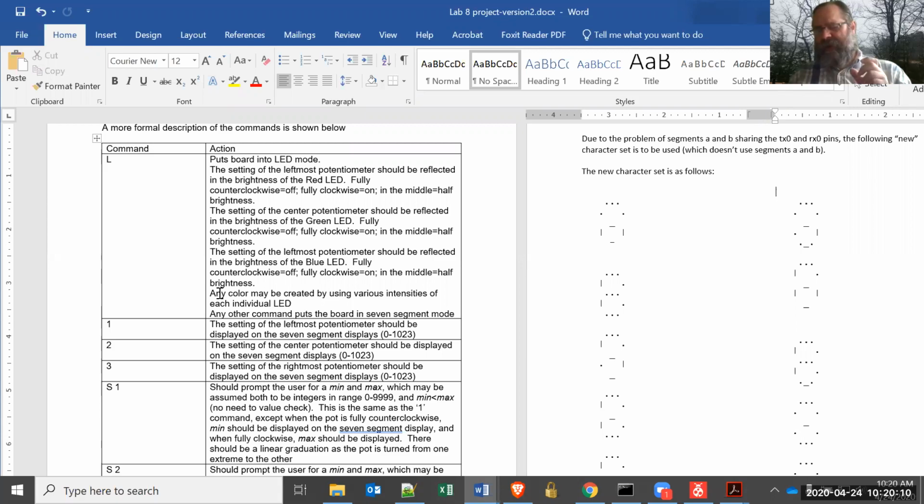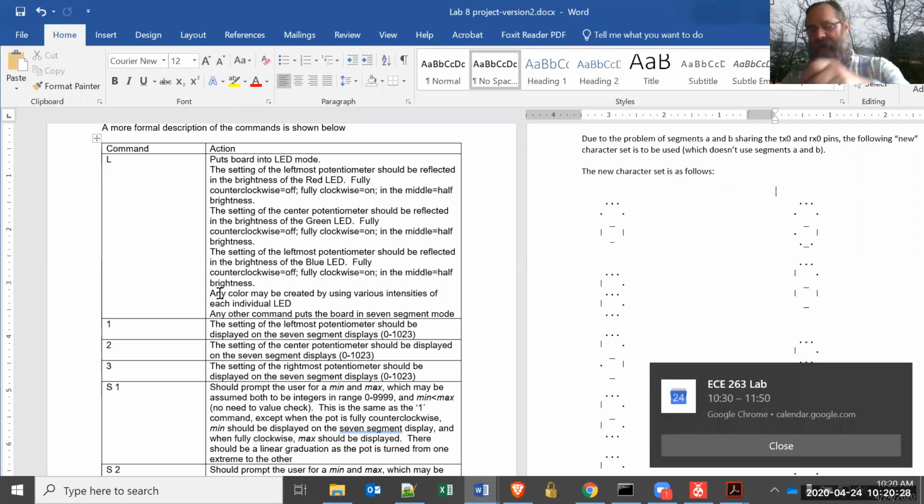So in addition to an LCD screen, you can also plug into there, I believe, another chip that was on another board, which will control 2 of these 7-segment displays using only 4 wires. And so you can actually just write what value and which digit you want to set.